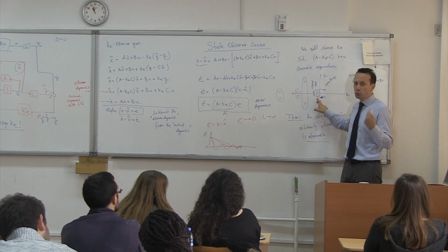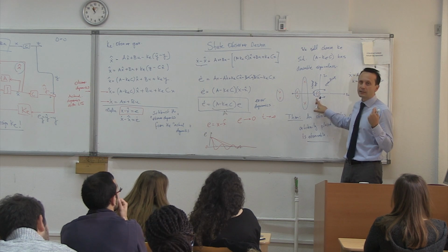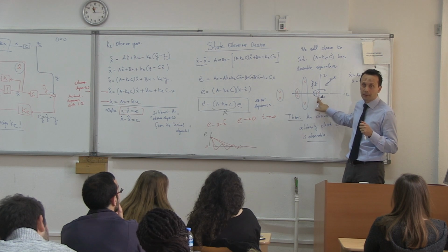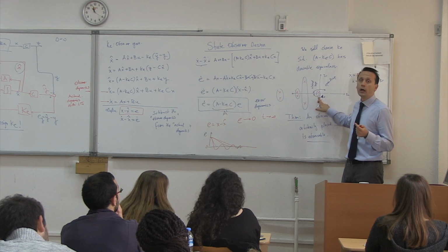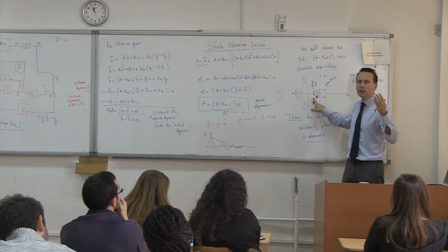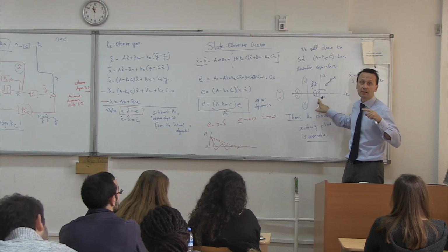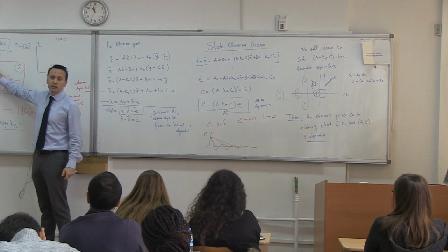I mean, is this something you could use at all? You don't want to use this, that's right, but there's another reason for it other than being slow. It is behind the closed loop system, which means who will converge first, the closed loop system or the observer? The closed loop system will. Can the closed loop system converge with wrong estimates of x hat? No, that's the problem. You see, I'm feeding x hat now into K.